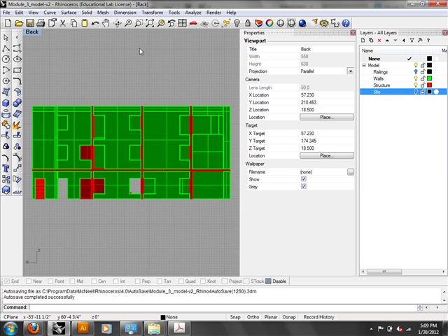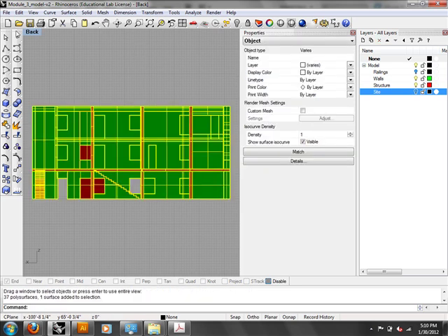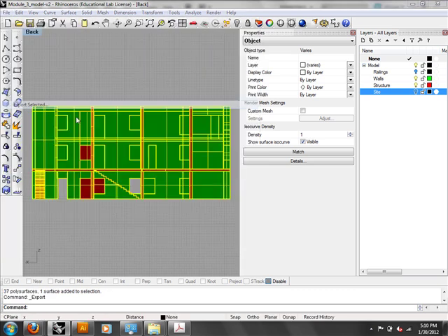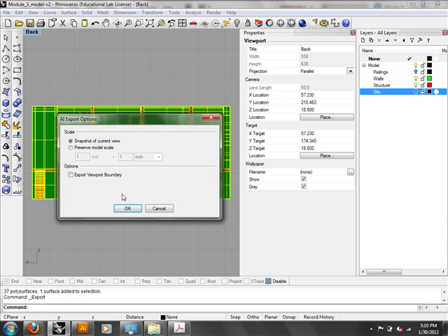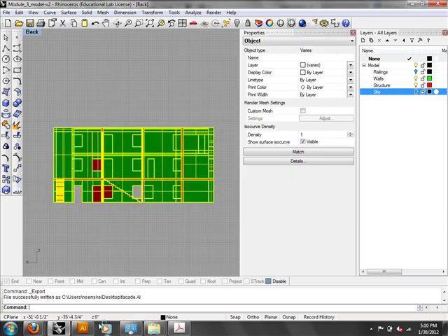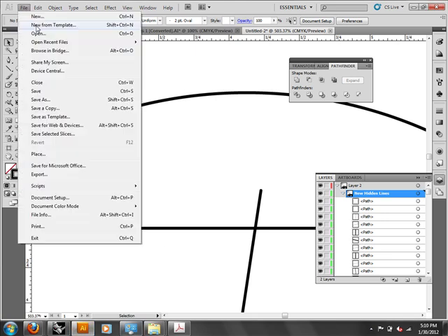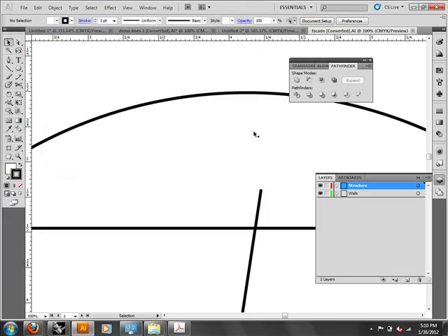Okay, so I have the right facade here. This is the back view, and I'm not doing Make 2D. I'm just going to go ahead and select visible. Then I go to export selected, and I'm just going to save it. I already had this file named anyway, so save a snapshot. And then if I open this up, again, I didn't do Make 2D.